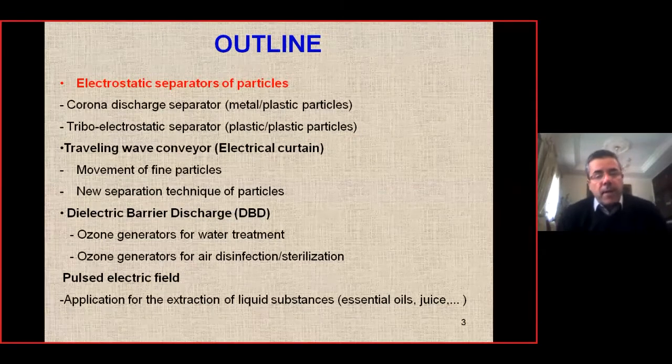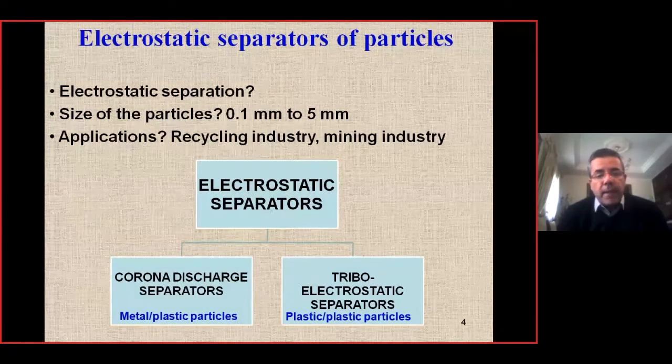Electrostatic separation is a technique used to separate a mixture of particles of size between 0.1 millimeter and 5 millimeter, for example a mixture of metal and plastic particles.